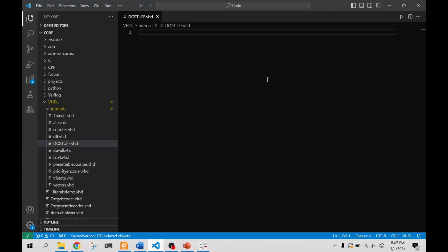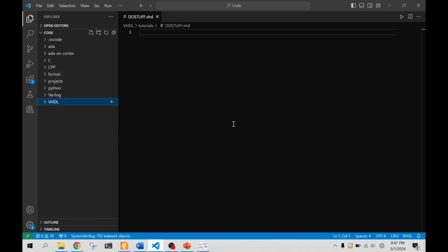Okay, so this is the first video in the series of VHDL tutorials that I'm going to be making. The scope of this first video is to just introduce you to the language and the structures, and then we're going to make a very basic combinational logic. So the first thing we start out with is library IEEE.